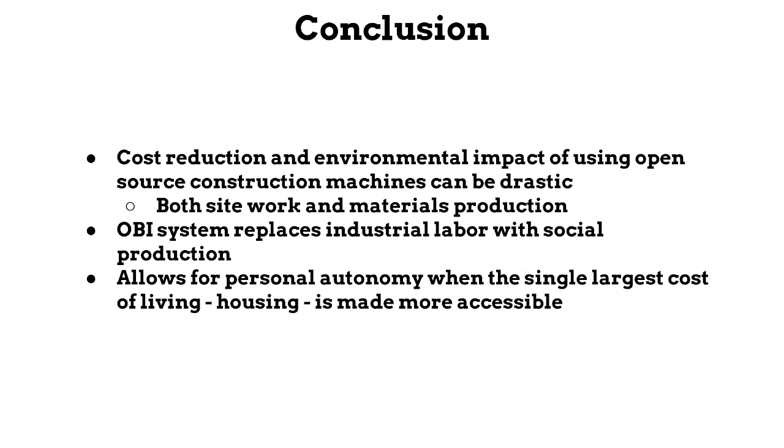Any other thoughts? What are the advantages of the induction furnace for melting scrap? Induction furnace is the most energy efficient way to get energy directly into melting steel. You can do flame stuff or resistive heating, but induction is the way. It resonates with the metal itself, so it heats up the metal mass, not like flames, which heat up everything. It's kind of selective, so it's highly efficient. You can get pretty good efficiencies. Using like an RF frequency to heat the metals? It's a high frequency power source.